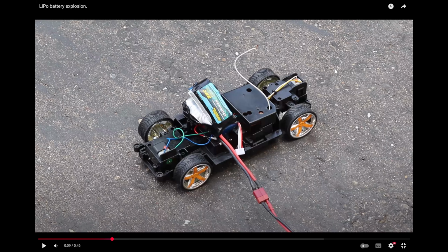So if there's a fire, don't try to put the lithium battery fire out. If you have to fight the fire, the only thing you can do is contain the fire around it and make sure that it doesn't spread. When we fly at the Ark, we fly over very short grass, which I don't think will spread. If you lit the grass on fire with gasoline, I don't think it would spread very quickly. Well, maybe if the whole thing was covered in gas, but if your drone crashes at the Ark and the grass is very thin, I don't think it's going to light the grass on fire. However, if you crash in tall grass, it will. That's one of the reasons we fly at the Ark, it's much safer.